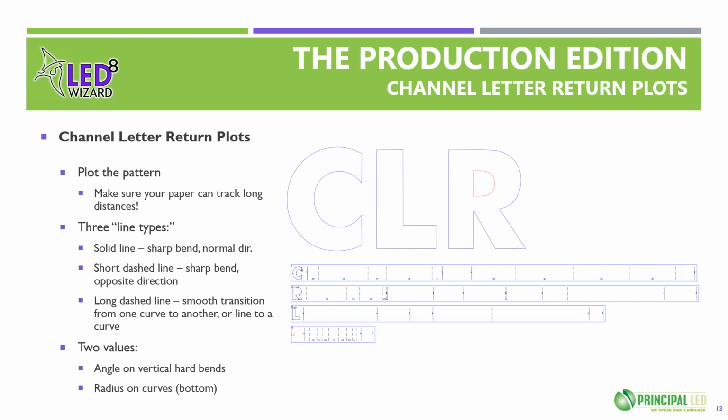So if you want to have that return overlap by, say, 1/2 inch, so you can clinch it, you would just add 1/2 inch to this pattern. The way this works is you also have an opportunity to set the start point for the loop. It's kind of too small to really see where I did that here, but you set the start point, so that start point becomes the start of the pattern. And as you go this way, you're going around the loop clockwise or counterclockwise for an internal. And then each one of these lines or dash lines indicates what you should do at that point.